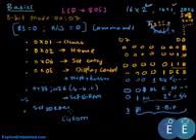So when you need to write or read from DDRAM, you use this command. Now this is all about the commands that we could send, because the register select is 0 and read write is 0. So these are the commands that we write into the LCD. We'll see the next combination in just a while.